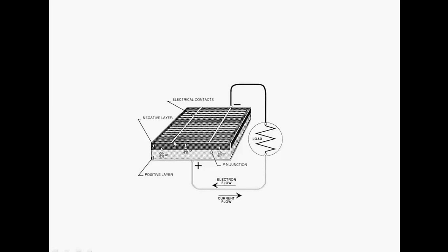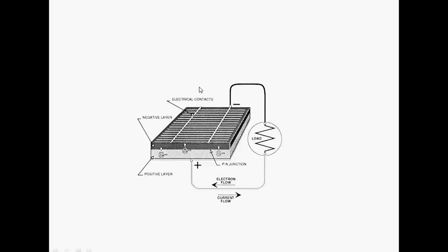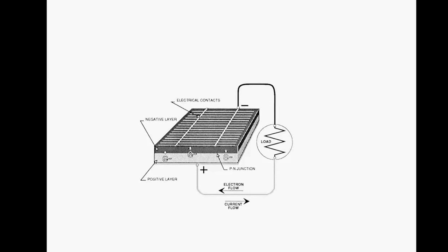So we draw some thin conducting lines using a photolithography process, in such a way that it should not cause any obstruction to the light falling on the n-type material, so that we can connect an electric contact to these thin lines and collect the current from the PV cell like this. This is the electron flow and this is the current flow as shown in the earlier case.